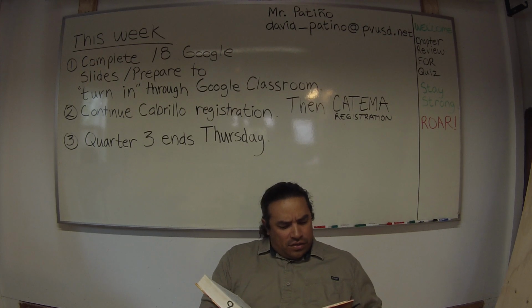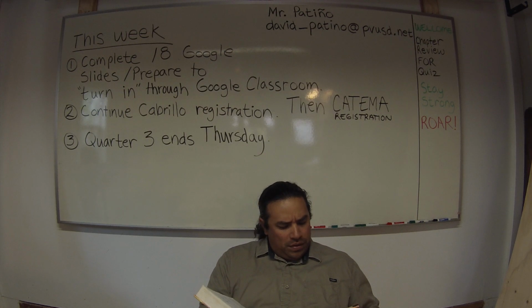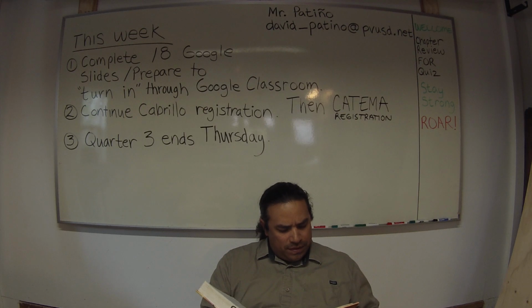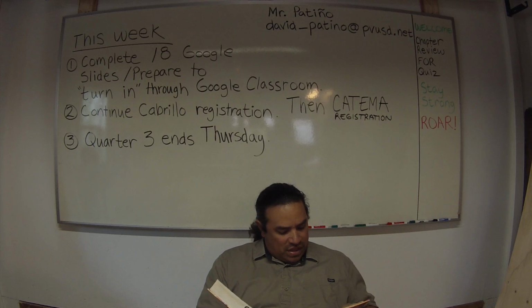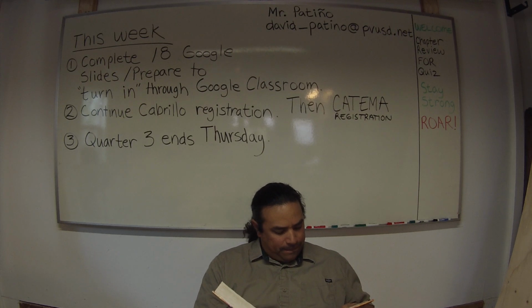Moisture content and shrinkage. Before wood can be used commercially, a large part of the moisture must be removed. When a living tree is cut, more than half of its weight might be moisture. Lumber used for framing and outside finish should be dried to a moisture content of 15%. Cabinet and furniture woods are dried to a moisture content of 7 to 10%. The amount of moisture, or moisture content, MC,